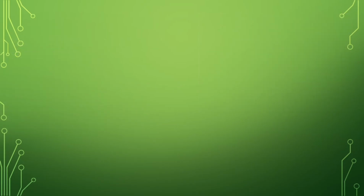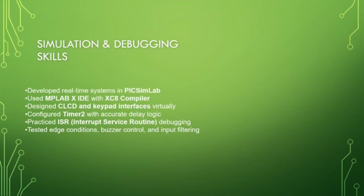Next, we have simulation and debugging skills. During the internship, I developed a real-time system in PICSimLab, used MPLAB X IDE with the XC8 compiler, designed CLCD and keypad interfaces virtually, configured Timer 2 and accurate delay logic, and practiced ISR, which stands for interrupt service routine, debugging, tested edge conditions, buzzer control, and input filters.